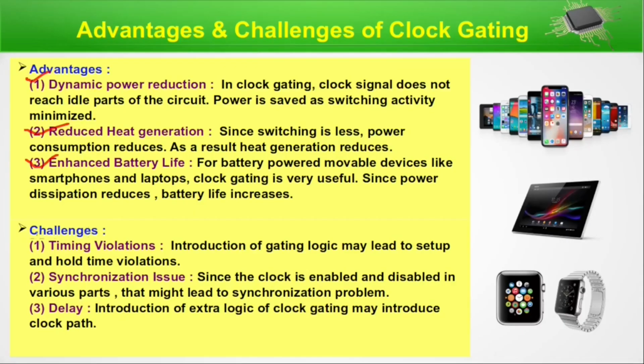And now challenges. Timing violations. Introduction of gating logic may lead to setup and hold time violations. We have seen in the multi-stage clock gating slide that in stage 1, the clock must reach first and then enable will come. So a timing violation may happen. That's a crucial factor in case of clock gating.